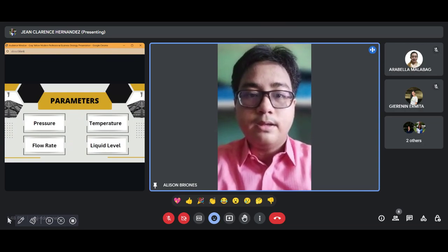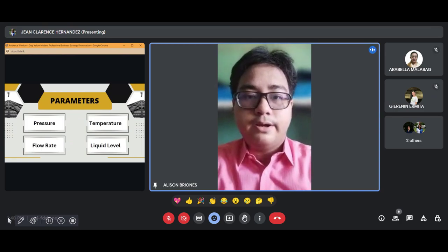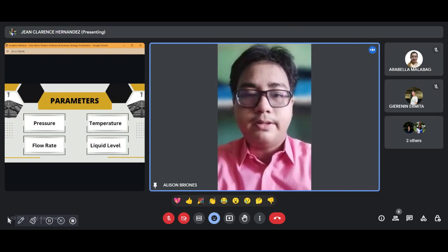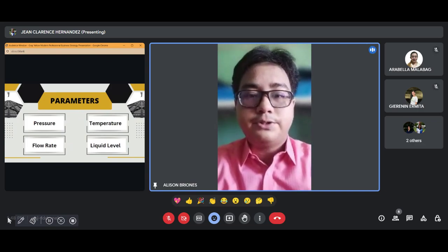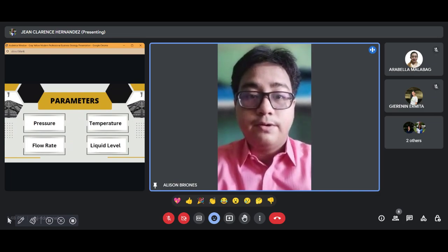Next, temperature is fundamental to the process as it influences the efficiency of moisture removal and glycol regeneration. Certain sections of the process require specific temperature conditions to achieve optimal results. For instance, heat exchangers help regulate temperature to prevent hydrate formation in the natural gas itself to ensure smooth transportation. Additionally, temperature control helps with the separation of water vapor from the rich glycol during the regeneration process within the reflux column.